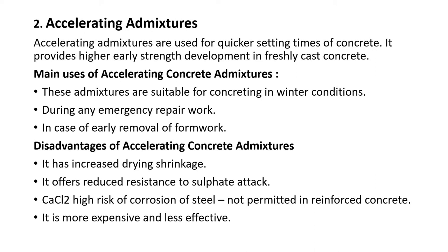Disadvantages of accelerating concrete admixtures: it has increased drying shrinkage. It offers reduced resistance to sulfate attack. Calcium chloride carries a high risk of corrosion of steel and is not permitted in reinforced concrete. It is also more expensive and less effective.